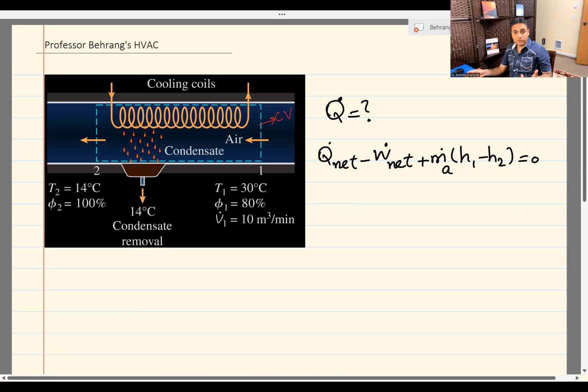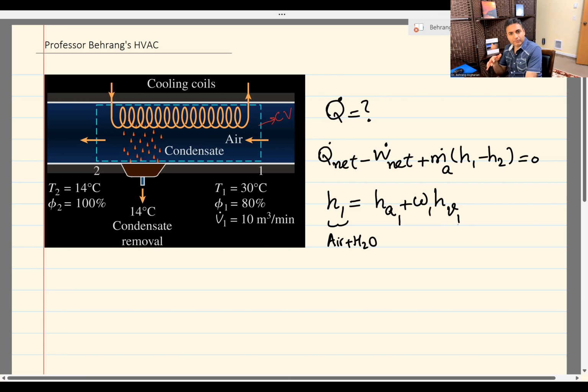One thing that you need to know when it comes to HVAC problems, and that's the background knowledge that I asked at the beginning of the video, is that when it comes to air and H2O together, we define the enthalpy of air in a very specific way. Like the enthalpy of air, this is the air and H2O together. We define it this way, that it becomes the enthalpy of dry air, the regular air, plus omega, the humidity ratio, times enthalpy of the water vapor, the vapor content of the air. That's how we define it. For example, for HA1, that would be omega 1 times HV1. And of course, this is the background knowledge that you need to know.